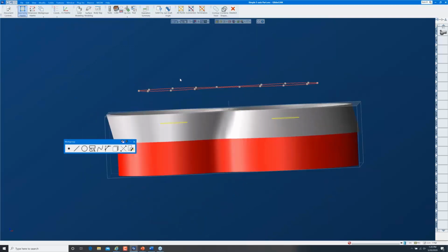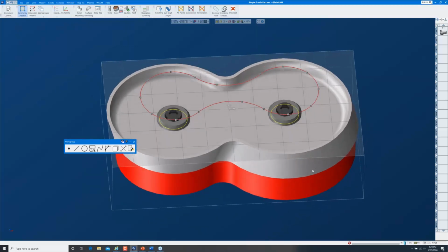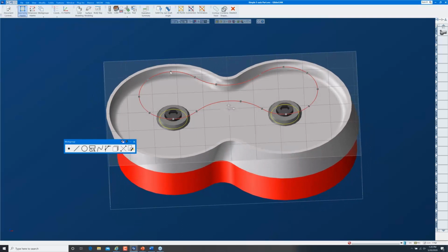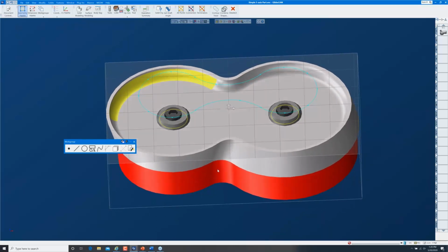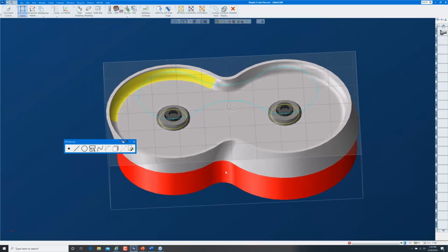And then I can test that quickly just by rolling this thing around and lining this up with the matching portion of the surface behind it, and get an idea of how much tilt is going to be required to get the tool there. And that's a good amount of tilt. I'm pleased with that. I'm not risking hitting the back edge of the part with my tool or my holder, and I can easily get to that undercut there.